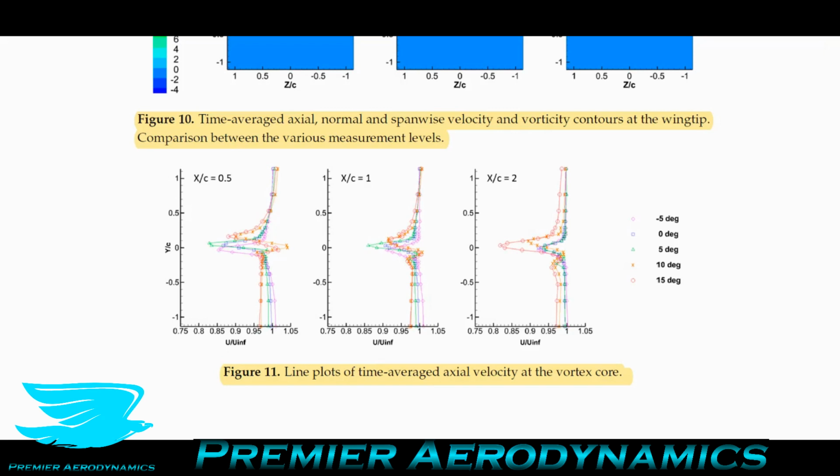So at these planes, the vortices are very tight, which means that they haven't expanded very much, and trying to measure all the parameters in there at all these different grid points is going to be very difficult. You need to get a very tight grid, and they may not have done that. It may be due to stall as well, I'm not too sure.